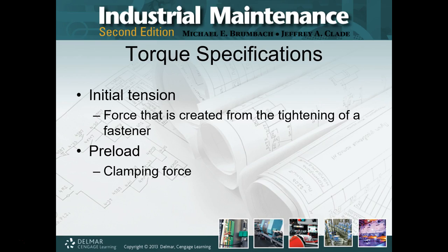and then they'll give it another prescribed twist to make sure that they know everything's fully seated, and they will let that bolt cool down. And as that bolt cools, it's going to shrink, it's going to contract. Well, as it's doing that, it's creating that internal force, that internal tension that's going to clamp the two pieces together.